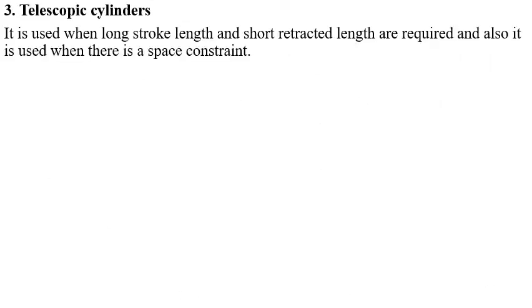And third main classification, telescopic cylinders. It is used when long stroke length is required or short retracted length is required. In such cases, telescopic cylinders are utilized.